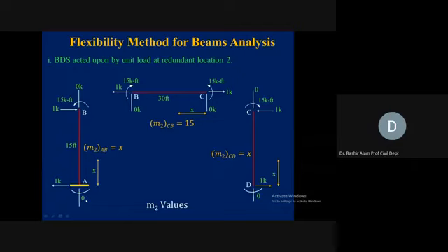To write now the moment equations for AB, again origin is A now, so 1 times X, not 15, 1 times X now, it is varying, so 1 times X we are taking, so X is here. For BC, we have 0 times X, so that is 0, but here it is causing compression, 15 kip-ft, so moment is coming 15 now. And here it is causing 1 times X. So plus X here, we are writing this one.